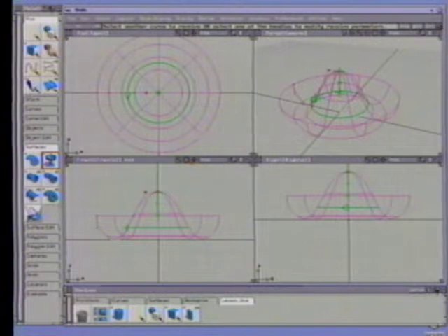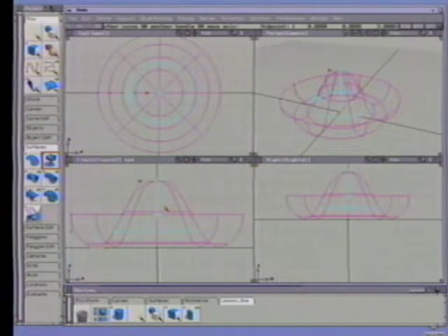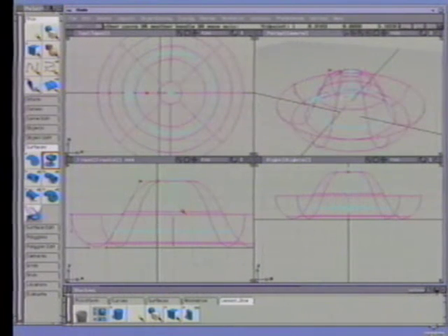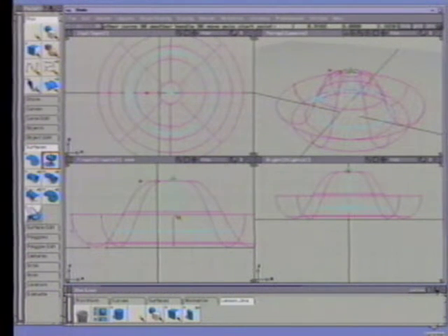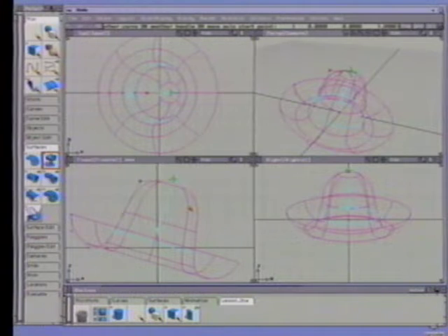In the front window, dolly and track the view until the hat fills the window. Click on the revolve axis line to pick it. In the front window, click-drag the axis line about one grid square to the right. The revolved surface automatically updates based on the new axis position. Click the bottom cross of the axis line as shown above. Enter 0, 0, and 1 to place this point back on the Z-axis.